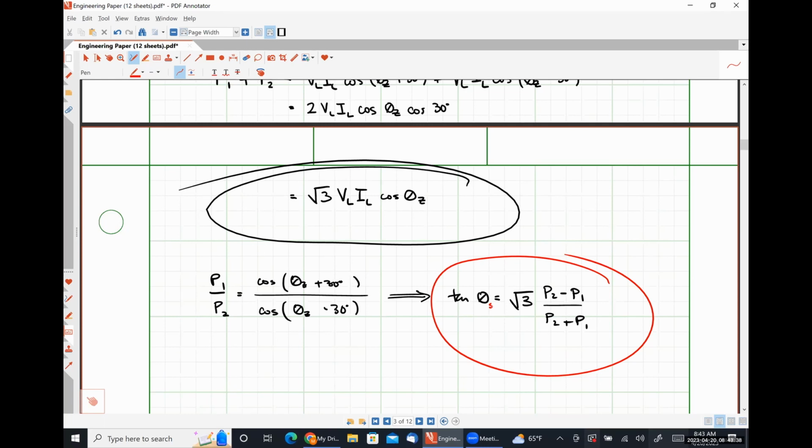So I've explained to you how watt meters are used and how you can use 2 watt meters, which is the standard industrial practice, in order to calculate the average power of any 3-phase load. It's simply just adding up the results of the 2 watt meters. And in a balanced system, you could figure out the power factor by simply using the readings from those watt meters. All right. So when you go get internships, literally you're just going to be connecting these things. Well, that's going to be a small part of your job. But if you're working with the engineering design team, trying to figure out what kind of feeders and all that kind of stuff you would need, this is a large part of it.